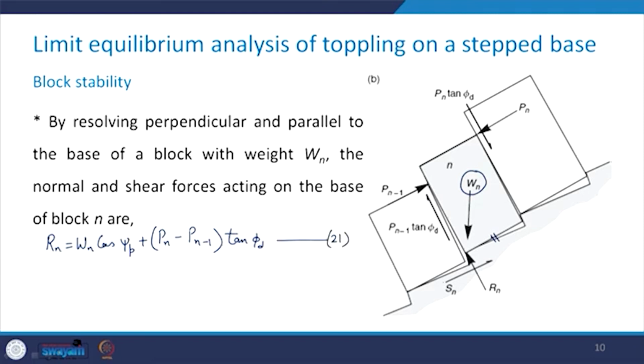And then if you take the shear force, it will be Sn equal to Wn sin psi p plus Pn minus Pn minus 1. So, there is nothing difficult. Take a look at this figure and then get the force equilibrium in the direction perpendicular and parallel to the base of the block whose weight is given by Wn.